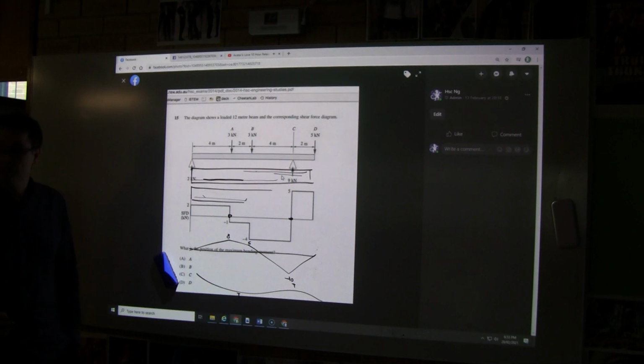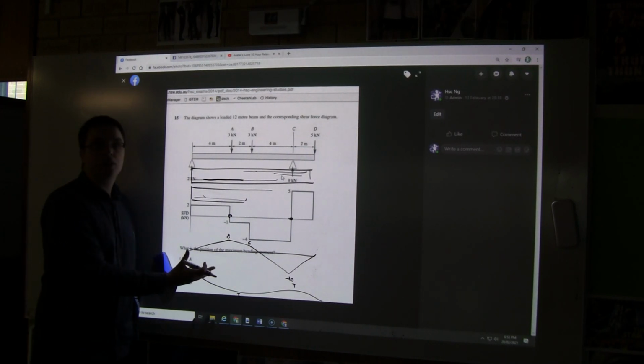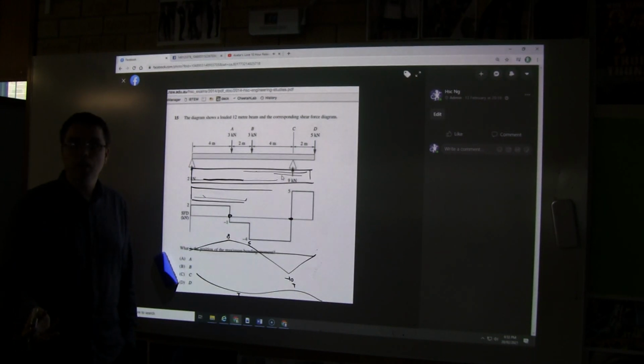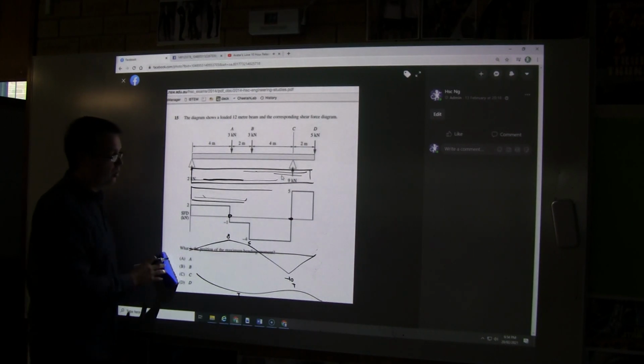I'm using this opportunity to say, why do we do bending moment diagrams? So you can see where we need to add extra steel. We can also see where we might choose a different material. We might choose a higher grade of concrete, not really with concrete, but theoretically. We could also reposition our loads. We might say this is not good enough, we can't deal with this, we're going to have to redesign. So there are some other considerations we might look at.